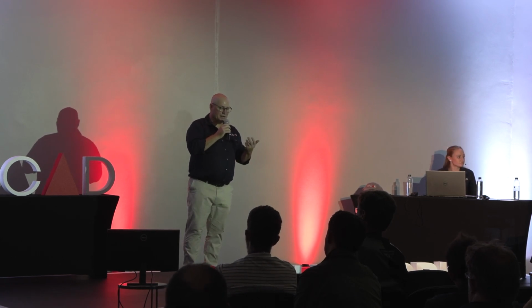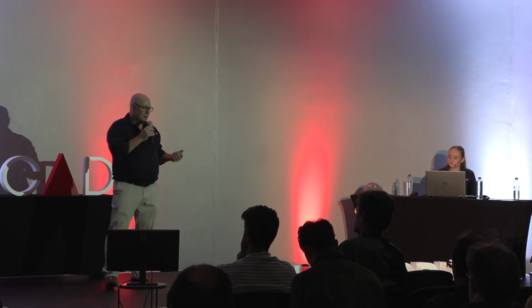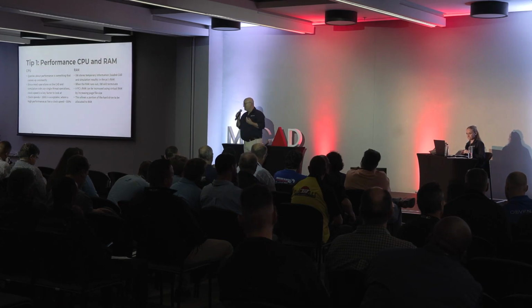Again, I'm not going to recommend that you run 8 gigs of RAM anymore and run a big page file for your normal modeling. Obviously, that hard drive is much slower. Remember, the RAM is a very high-speed memory, and your hard drive is a much slower speed. But if you do a massive render or simulation, and it needs to create a lot of files, speed is not necessarily the big thing for accessing that information.